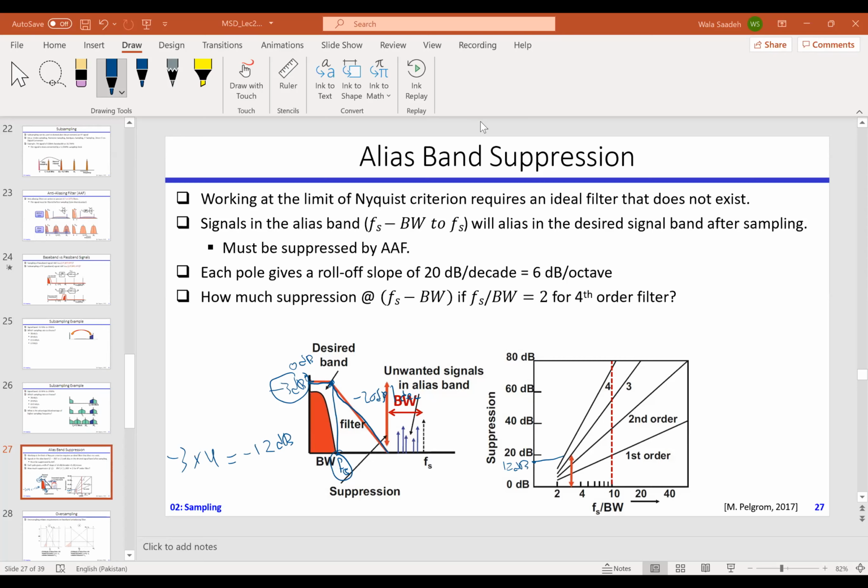No question on this? Okay, is there any maximum limit on the sampling frequency you can use? Yes, in a sense that you need to be careful. You don't want to increase your sampling frequency too much, because your power consumption will also rise accordingly. You need to be careful when you design for such high frequencies. You will run into other issues.